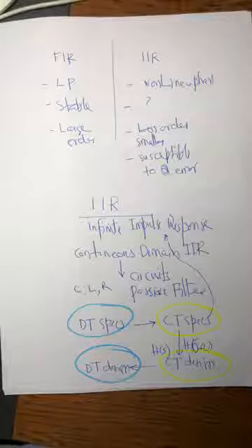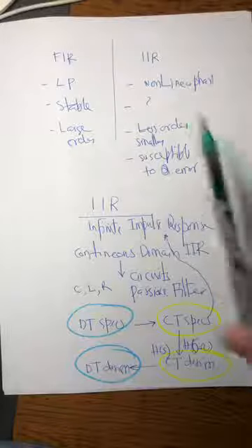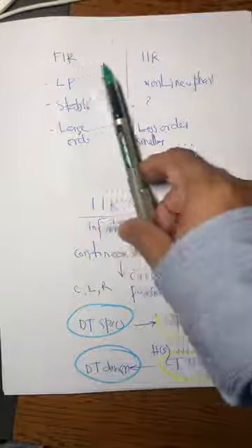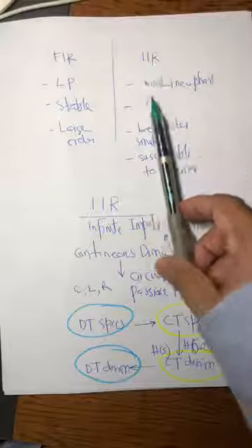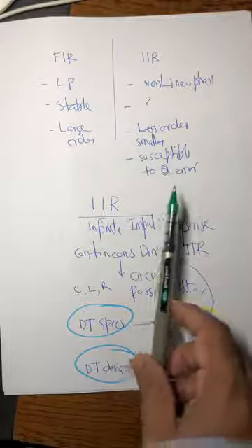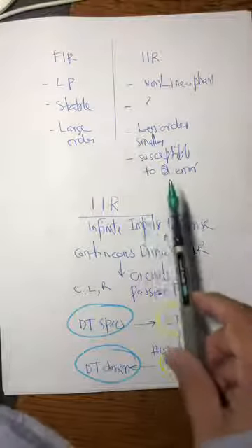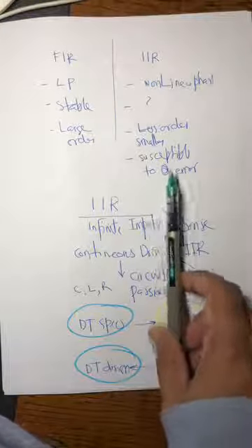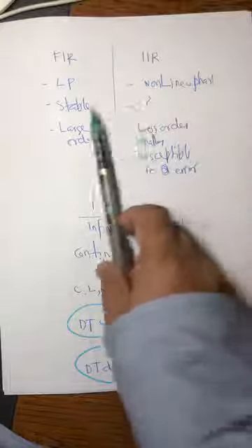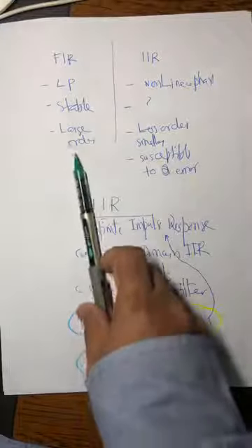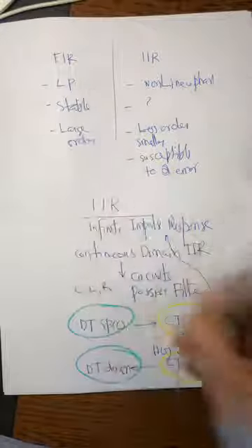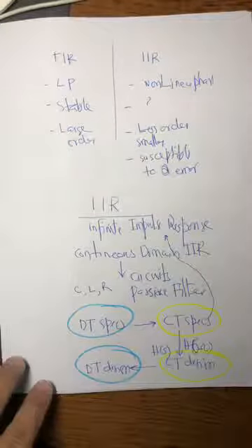And then again, last time we spent a little time learning about the comparison: why should we design an IIR or an FIR filter. And we said IIR filters are computationally effective because you need a smaller number of coefficients, but then you have also done a lab where you need to deal with coefficient quantization and nonlinear phase, whereas with FIR you spend more in terms of computation, but you have comfort that you don't need to worry about stability, and it is also linear phase.